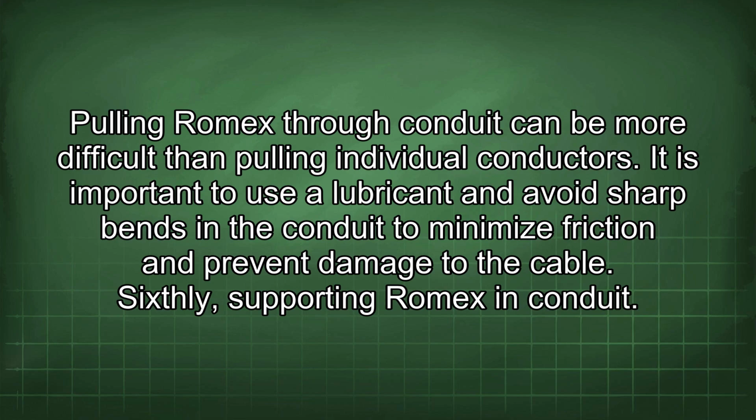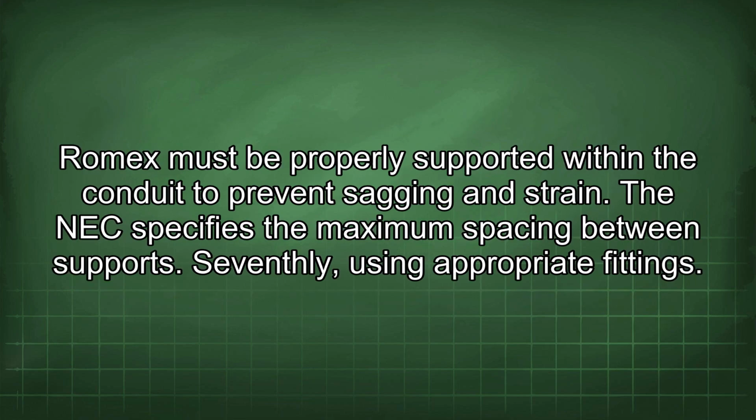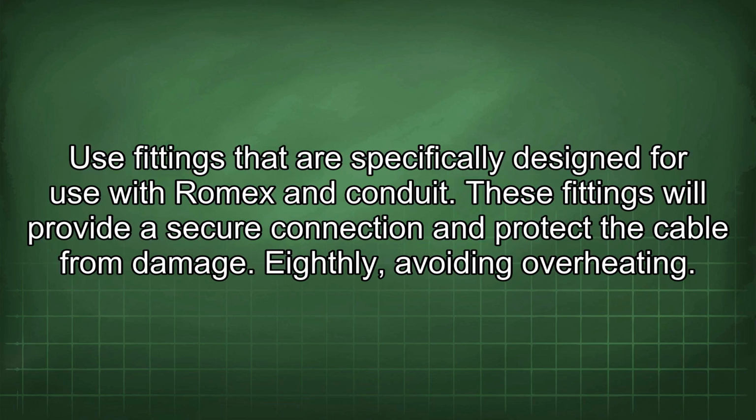Sixthly, supporting Romex in conduit. Romex must be properly supported within the conduit to prevent sagging and strain. The NEC specifies the maximum spacing between supports. Seventhly, using appropriate fittings. Use fittings that are specifically designed for use with Romex and conduit. These fittings will provide a secure connection and protect the cable from damage.